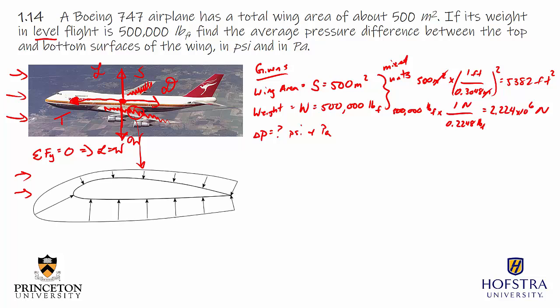And if I look at what a typical pressure distribution might look like over an airfoil, we see that towards the leading edge there is a high pressure, and this will be due to a stagnation point. And then the flow going over the top gets accelerated, reducing the pressure, and the flow going over the bottom creates a higher pressure. So we've set up a pressure difference. And if there's higher pressure perpendicular onto the surface on the bottom and a smaller pressure acting on the top, this will generate an overall vertical force in the lift direction.